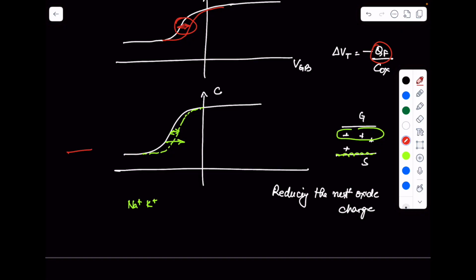So for example, what I'm trying to say is this is EC, this is EV, right? Aluminum would be somewhere here, copper would be somewhere here. So if I start off with copper, right when the bands are formed, that is when no voltage is applied, there's already a large field between the two. So therefore it's going to be easier to invert the surface.